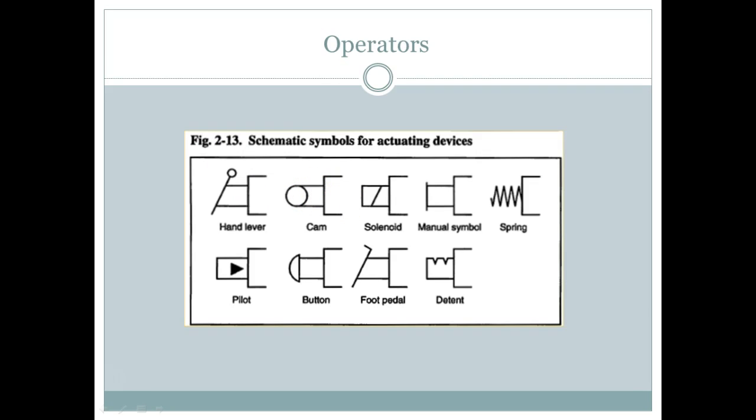So what happens is my solenoid is not going to have a lot of area out there on the end. So force is equal to area times pressure. Your solenoid can't generate a lot of pressure, right? You understand? So it would take a really big area. Well, we don't have a real big area to work with.